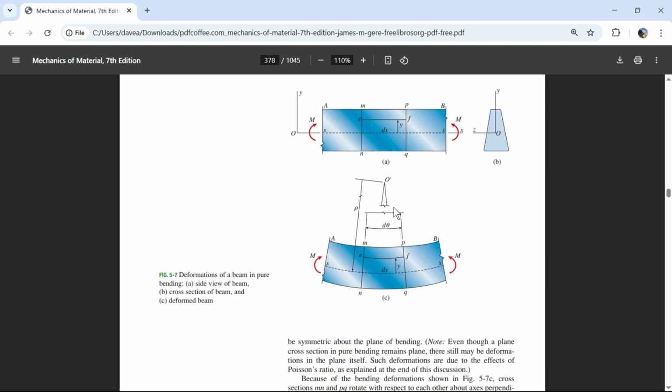I guess the take-home point is that bending creates big deflections because in between every 2 rows of atoms, you're getting them to crunch in at the top and lengthen at the bottom, and you're getting a small change in angle to form. And that's going to be each little slice of this beam continuing with that change in angle. And this is the definition of a circle.